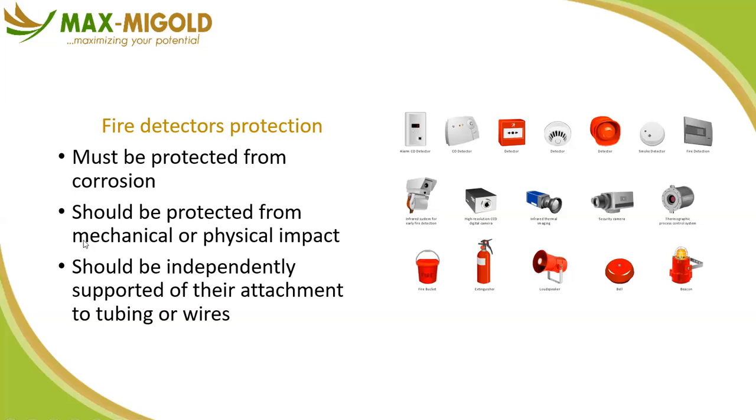In most cases now, they even come in IP65 rated components, meaning that it can actually be placed outdoor without fear of corrosion. But we should ensure that even where we are placing this equipment, we guarantee some level of protection from corrosion, from direct contact with water or rain, and of course, not come in contact with corroded iron or metal pipe, right?